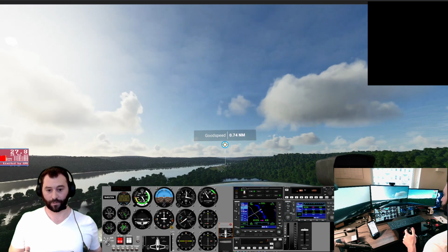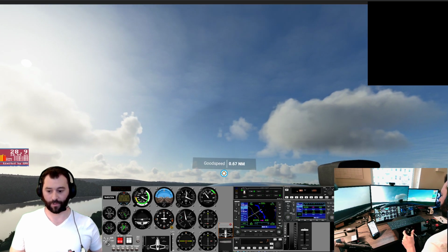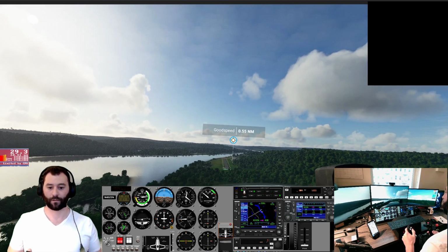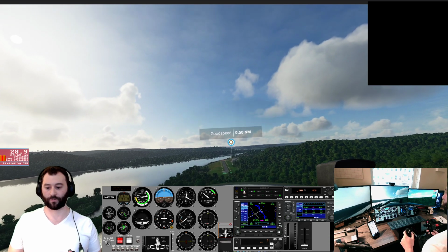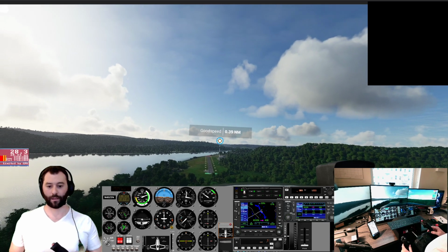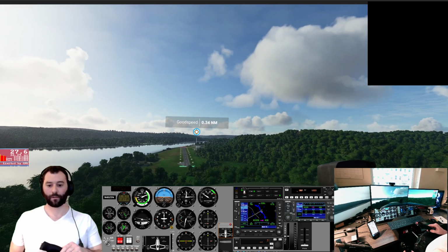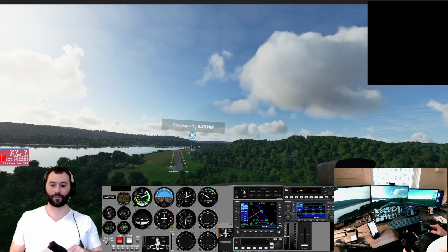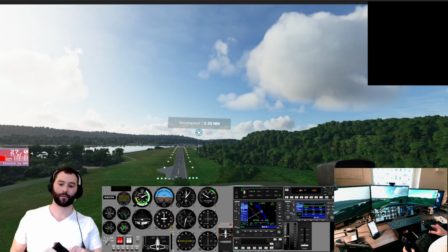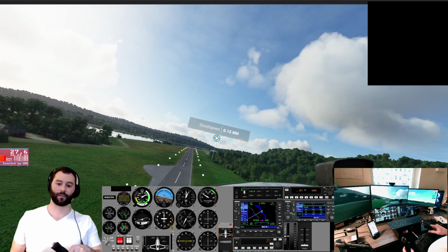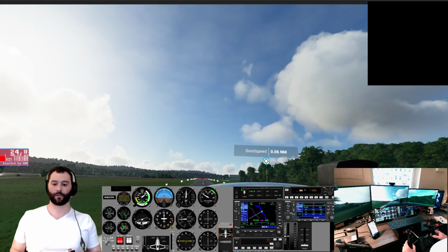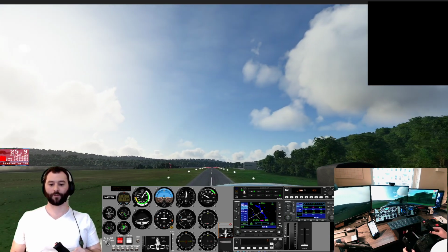Alright, we need to get to 80 so that we can throw some flaps down. Let's go full flaps. We definitely have it made. At this point, we want to make sure we're not too fast and too high. So we're already high, so I'm going to kick it into a slip. Let's see if we can get slowed way back to make this landing. I think we got it made for sure.